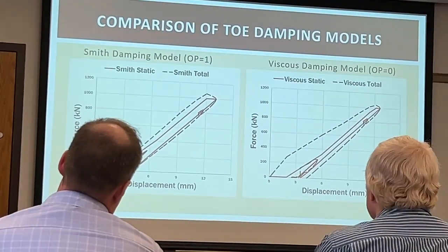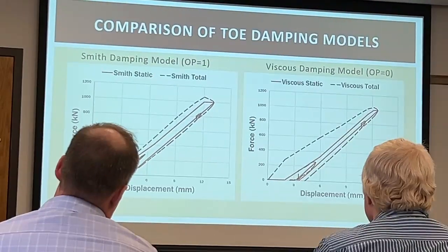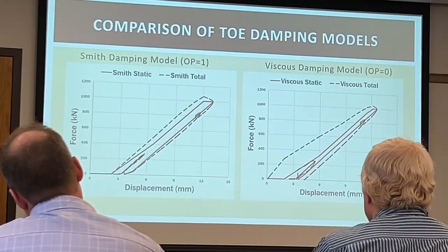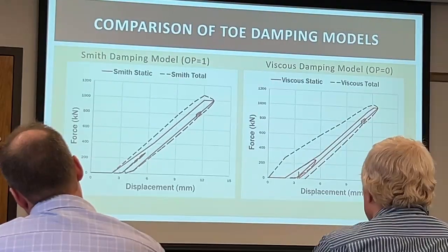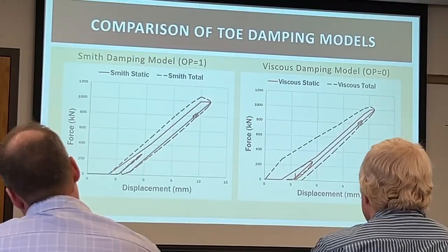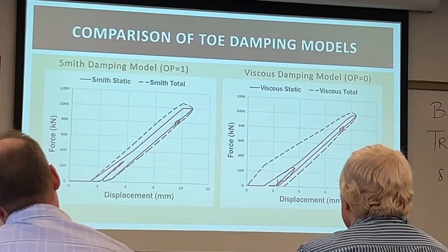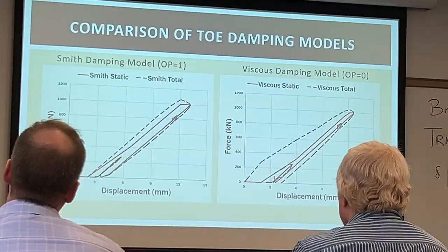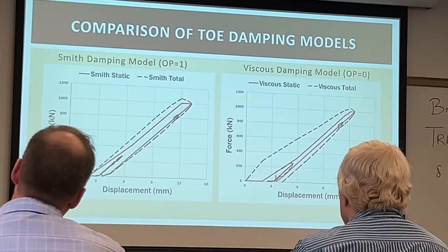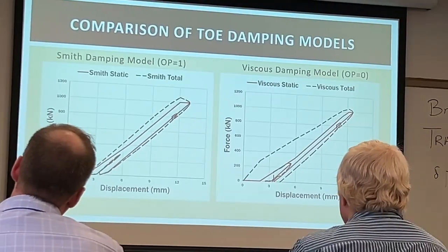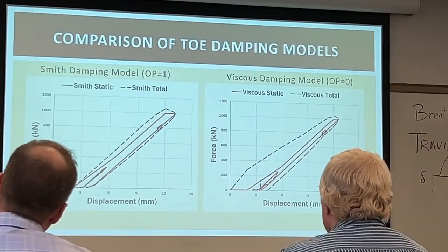And so what that means is if we are using the mobilized resistance, and this is at the pile toe, and if we have a gap which says that there's no resistance until that gap closes, as if the pile is bounced off a rock, then mobilized resistance through here is 0, and therefore dynamic resistance is 0, so you'll have a free end for a longer period of time. And as a result, you'll see a very deep tension response.